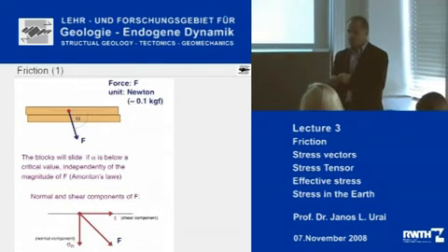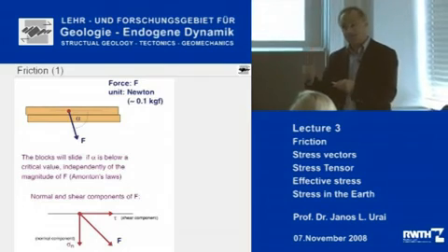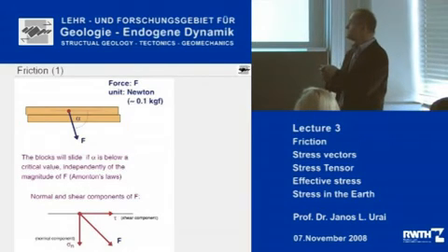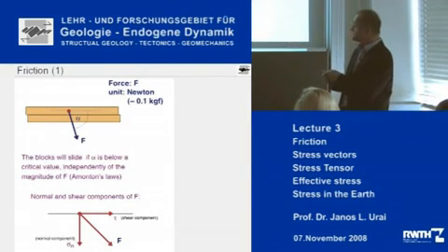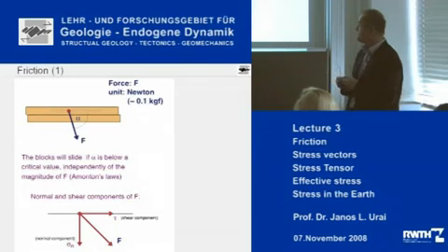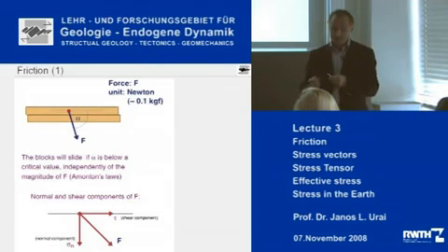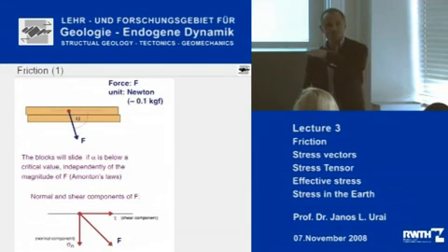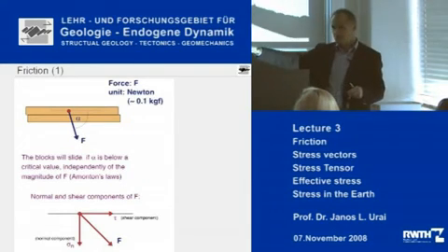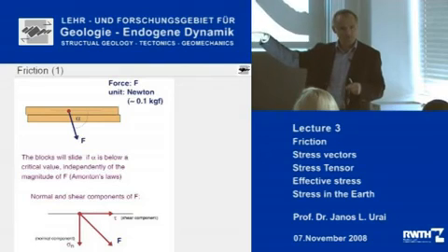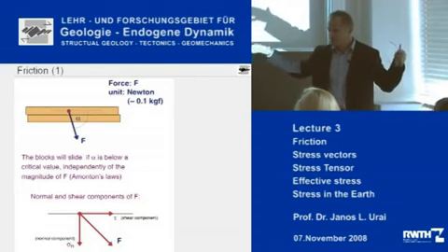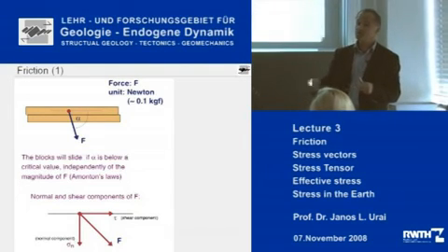What I also know is the friction coefficient, which is the tangent of the friction angle. It is 0.85. The acceleration of gravity is 9.8 meters per second squared. And what I want to know is the shear stress, tau, which you need to move this block. So imagine it is a huge block of sandstone, 1.5 meters high. It's enormous, it's very, very heavy. And I'm asking you the stress